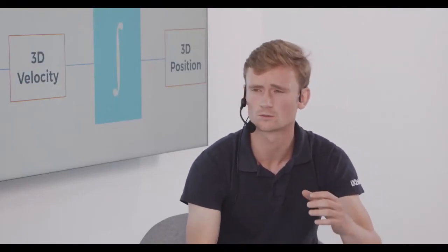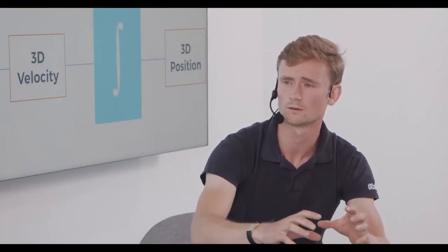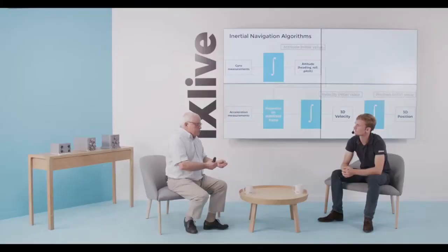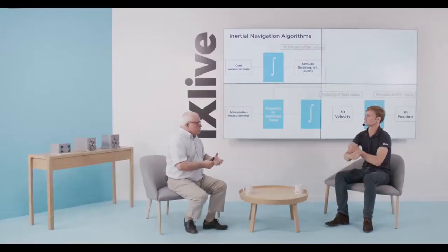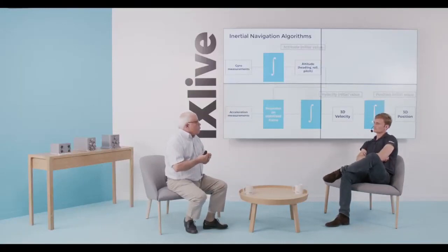Okay, well, interesting. So we talked about different methods. Some are for a static vehicle, others are for a vehicle that's moving. What would you recommend? Well, no general recommendation. It always depends on what constraints you are able to accept. If you want to have heading in static mode, either because you need it or because you don't want to start the run without this information, you need at least one of the first three methods.